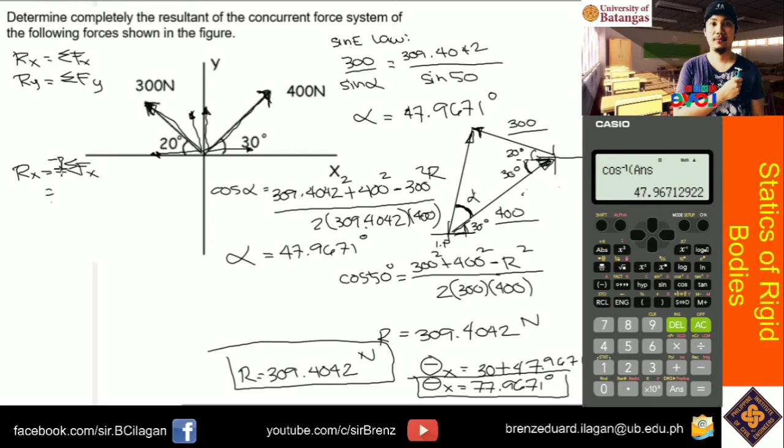So Rx, let me write it here. What are the horizontal components of our forces? Let's start with the 400 Newton. What do you multiply it by to get its x component? Right, so 400 cosine 30. And then 300. What will be the sign of your 300? Where is its x direction? Its x is going to the left. If going to the right is positive, then since it goes to the left, that will be negative, multiplied by cosine 20. Okay? So what will be the value of your Rx?